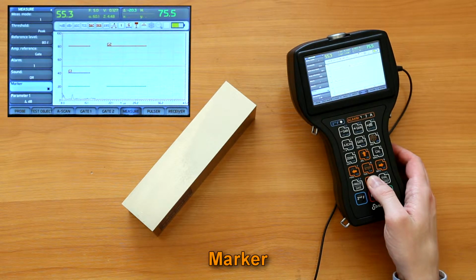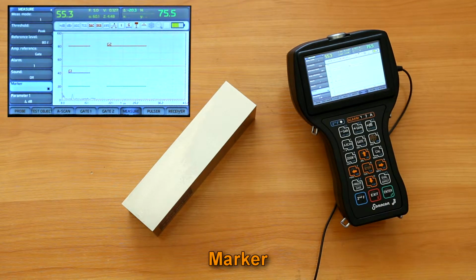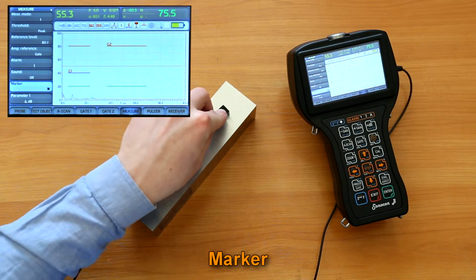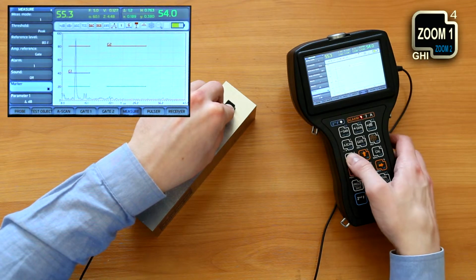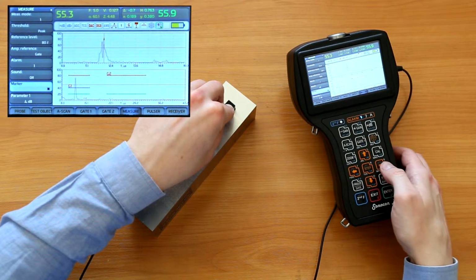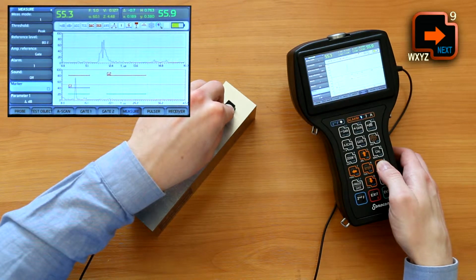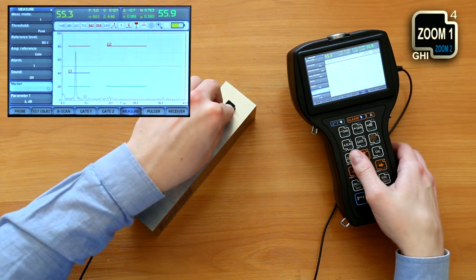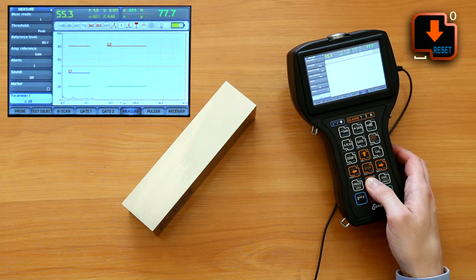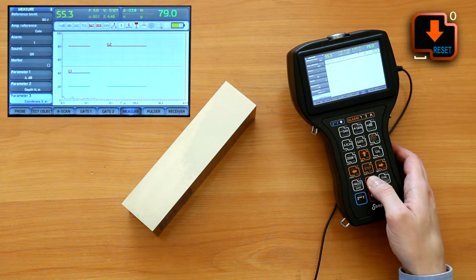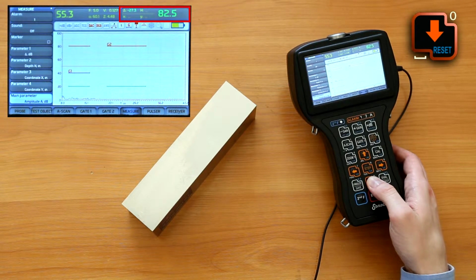Marker toggle, if on, shows in a zoom window as a vertical line with arrow, indicating the signal point which is used for the measurement. Further, 5 items concluding this menu allow choosing 5 indication parameters to show on the information panel, 4 small and 1 large.